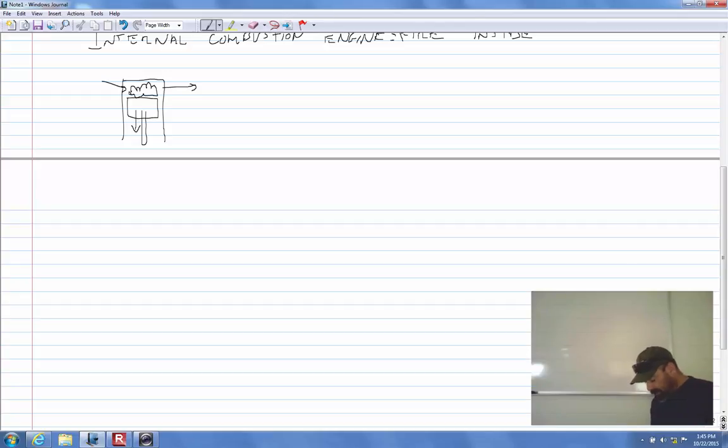Let's see, they're doing the math, continuing along. We know we're going to go 2,000 meters to go that distance, right? Because it's a 1 in 20 ratio. So to climb 100 meters is going to be 2,000 meters. At 60 kilometers per hour, it's going to take about 2 minutes. So now we can convert it to kilowatts. Our 981 kilojoules is the energy required to climb that hill. It takes 120 seconds or 2 minutes. That gives us 8.2 kilojoules per second, or 8.2 kilowatts.